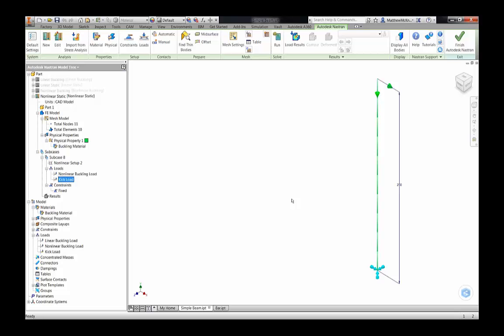It's exactly vertical. It's fixed perfectly at the base. The load is applied directly down through the center of the part, and it's applied exactly along its axis. So there's really no flaws in the design. So if you were to analyze the structure, we really need to be able to excite the buckling phenomenon associated with the failure of this part.